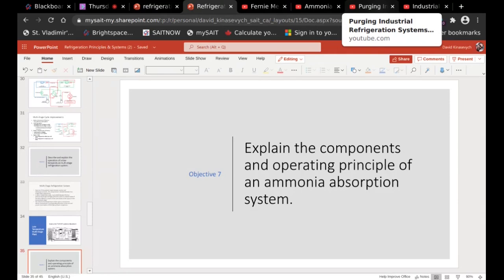Now, how do we know that the deaerator is working? We look at the pressure and temperature relationship, and we see that the pressure in the vessel equals the saturation pressure at the temperature of the saturated water in the deaerator. And we go, oh, yeah, they agree. The deaerator's working. But when the deaerator pressure is considerably greater than the saturation pressure of the saturated water in the storage tank of the deaerator, we go, oh, we've got too much pressure, our deaerator's not working. And again, our concern about a deaerator not working is dissolved corrosive gases.